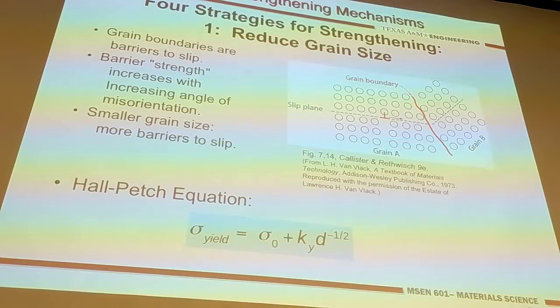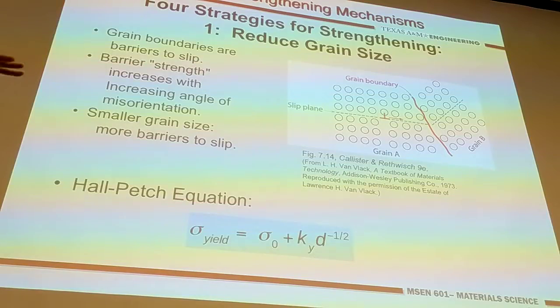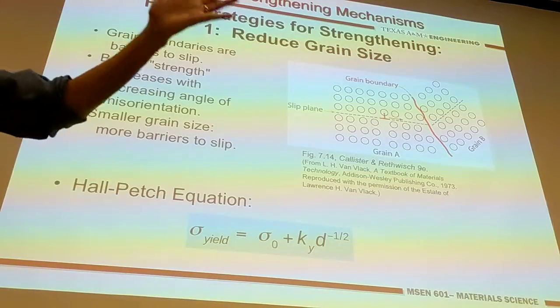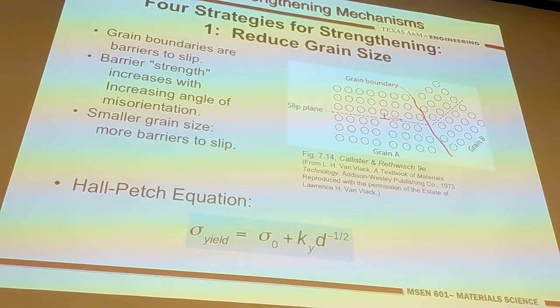In metal, you can easily have slip of dislocation moving in the metals, for example single crystal or polycrystal. As long as you identify the slip system, then on a certain load you will have the corresponding stress applied to those planes and slip directions, and up to a certain limit, the critical resolved shear strength, you will initiate the slip of dislocation. So you will propagate dislocation and generate the plastic deformation.